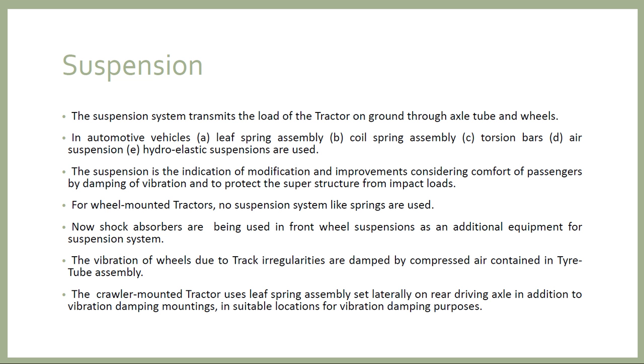So in the wheel mounted tractor we use the shock absorber kind of suspension system, and in the crawler mounted tractor we use the leaf spring assembly as a suspension system.